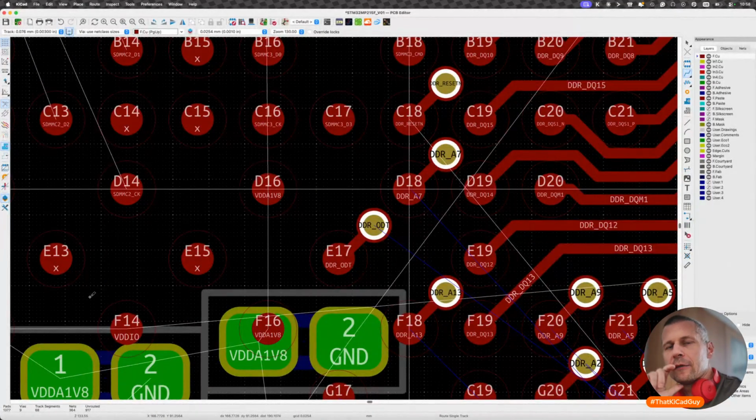Shortly, again, I ended up with JLCPCB. They have special 3 mil limits for both thickness and clearance for BGA fan out. They specifically mention that these limits are for BGA, and it's okay for short tracks to use this small clearance and track width, including the very thin annular ring.